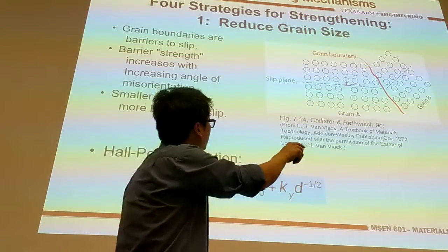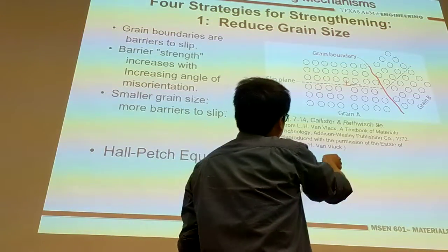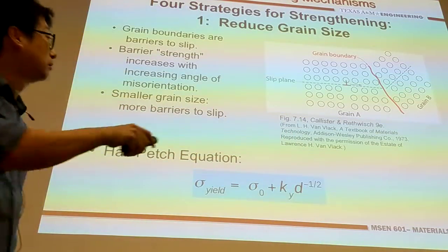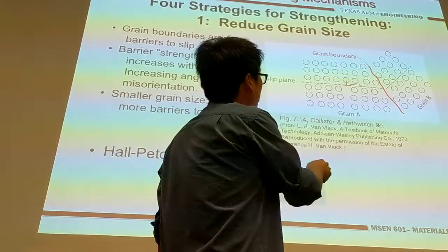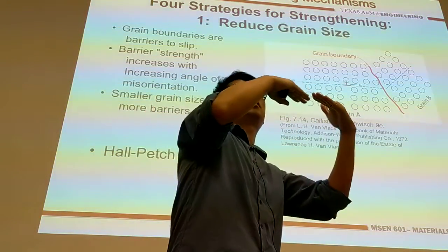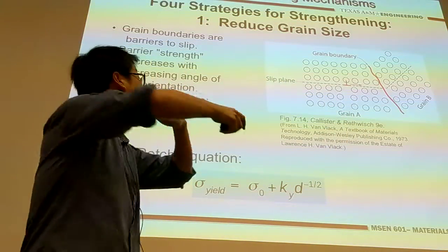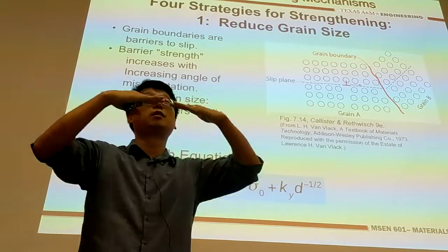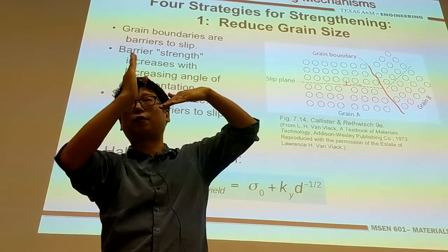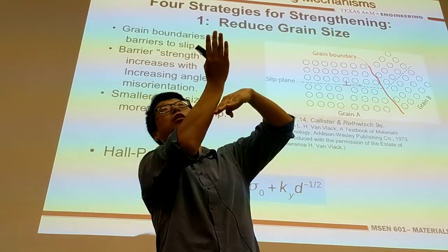Then what happens is that this dislocation, for example, you want to force it to move from the left-hand side to the right-hand side. If these 2 grains are perfectly aligned, what will happen? It will propagate easily. Perfectly aligned meaning it is almost like a single crystal, right? I mean, this is the corresponding slip plane, this is the slip plane, right? However, if I tilt the slip plane, what will happen? It will be very hard for this half atomic plane to move and rotate, switch direction to the other plane.